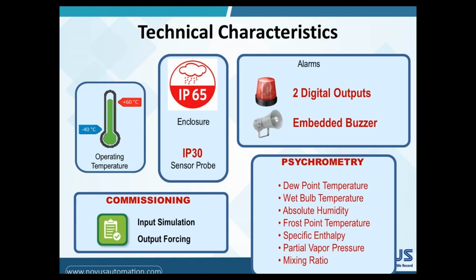The device has 2 alarm outputs with N-type transistor. Any alarm can be set as low, high, inside band, or outside band. It can be configured with the set point, the hysteresis, the output condition on sensor error, low or high level, and the timing type. It can be pulse, delay, intermittent drive, or normal.